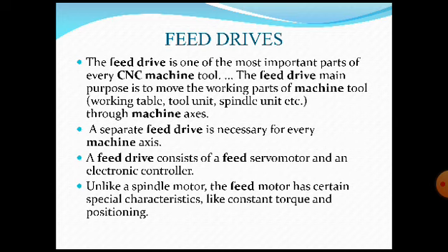Whenever we transmit the motion from the servo motor or the stepper motor, that rotational movement is converted into linear motion. Again, the feedback is taken back and sent to the controller to check whether the table has moved the required linear distance or not, which we have discussed at length while discussing the closed loop. Try to understand the closed loop control system.